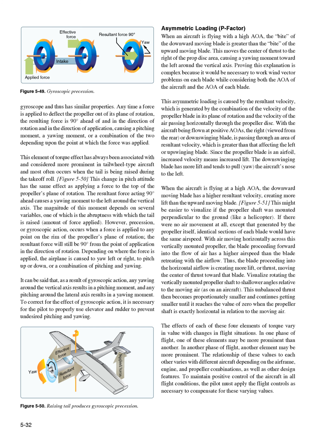This unbalanced thrust then becomes proportionally smaller and continues getting smaller until it reaches the value of 0 when the propeller shaft is exactly horizontal in relation to the moving air.